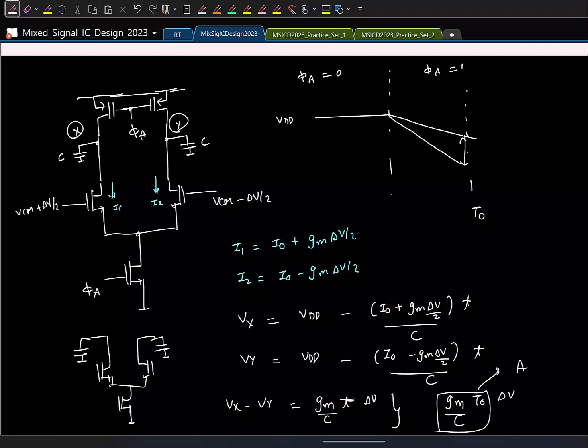So this gain is enough as a preamplifier, you can actually get very high gain. Remember, we are looking at a parasitic capacitor. You can have a very small capacitor, and then if you wait long enough, and if you have a large enough GM, you can easily get a gain of even 10. It's not impossible. In fact, people do that all the time. Okay, so this is a dynamic amplifier, and in this case, when are we drawing the current from the supply?